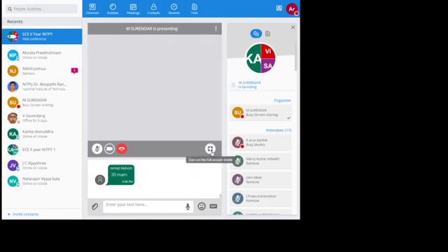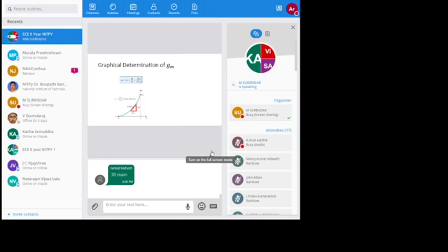So when we calculate the slope at the Q point by drawing a tangent to the curve, we will get the value of the transconductance GM. This GM is nothing but del y by del x, that is the slope, right? dy by dx is equal to the slope. So GM is equal to del y by del x. Del y is your y-axis, that means del of ID, and del x is del of VGS. That's why we have GM is equal to del of ID divided by del of VGS.